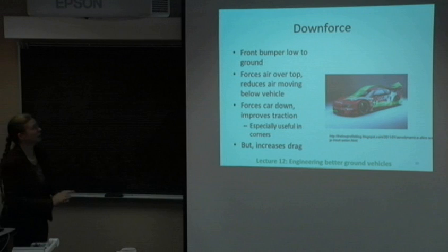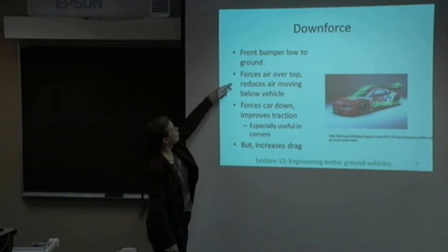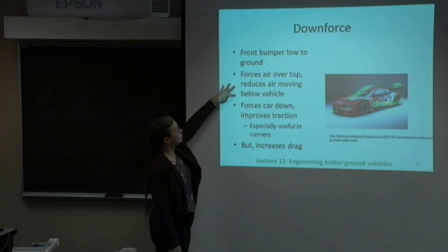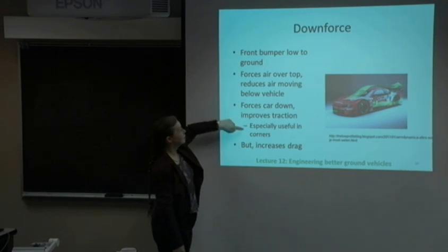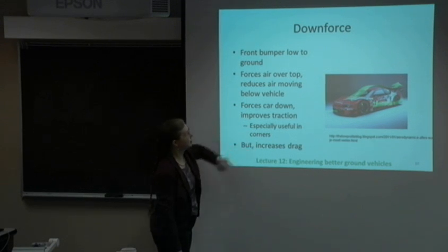So downforce. Here's another example. Make the bumper low to the ground in the front, forces the air over the top, reduces the air moving below the vehicle, improves traction. This is really good in corners if you're a race car driver. But it increases the drag, not decreases it.